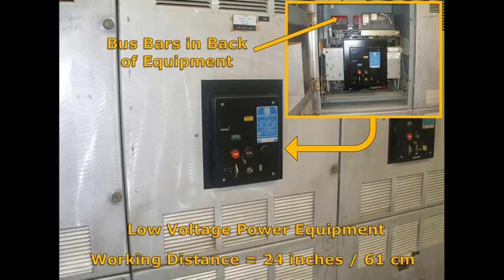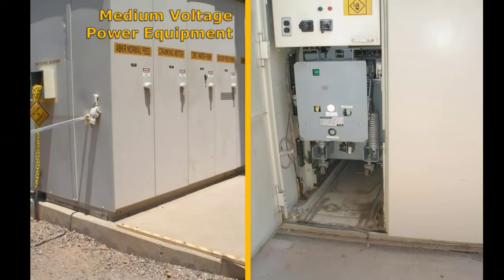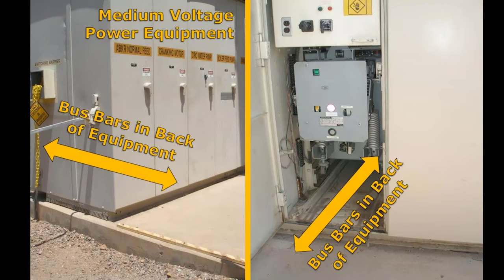But at any rate, however the arc flash incident energy calculation is performed, it has to be based on some form of a working distance. For medium voltage equipment, what IEEE 1584 provides is 36 inches. Again, similar logic that the energized components are going to be back in the cubicle. And so 36 inches is often cited here.